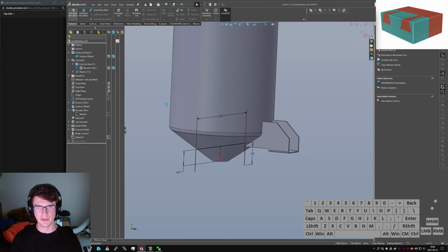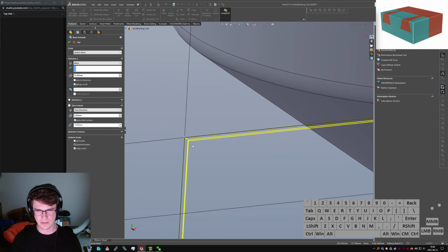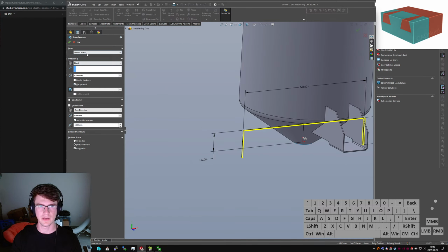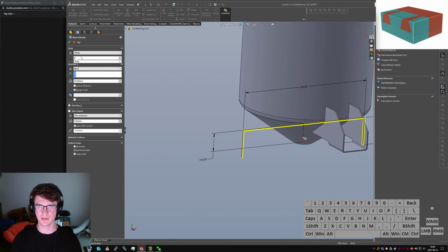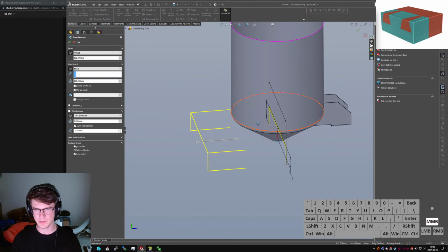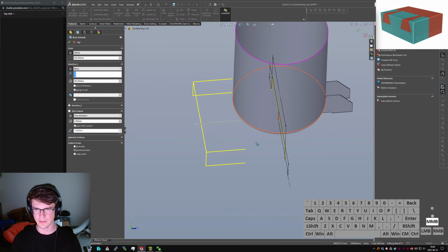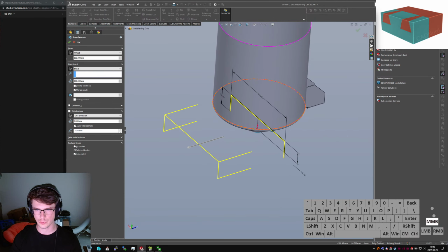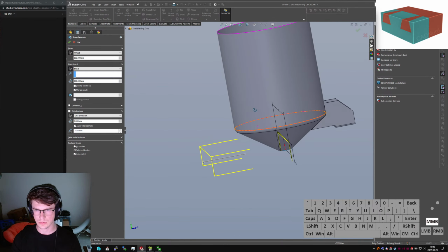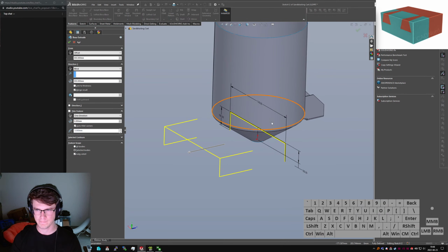We'll do an extruded base, same as before. Thin extrude with auto fillets, just because it makes things nice. And we'll start with an offset. Come back maybe 300 millimeters in the other direction. Make it 300 millimeters long. Whoops, flip direction. Yeah, that looks pretty good. I think I might try and... How do I want to do this?